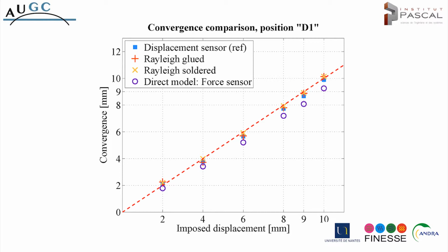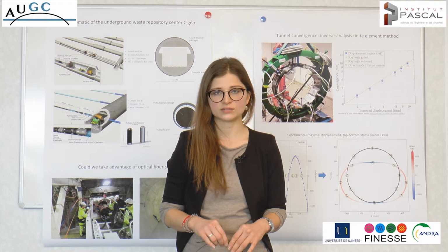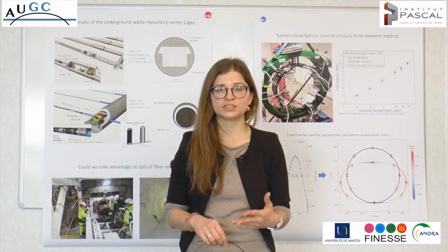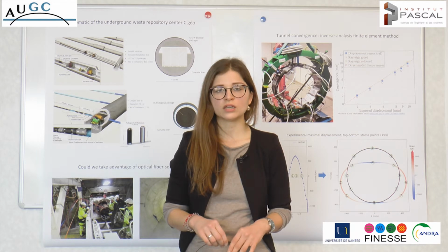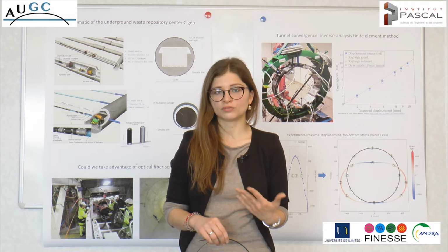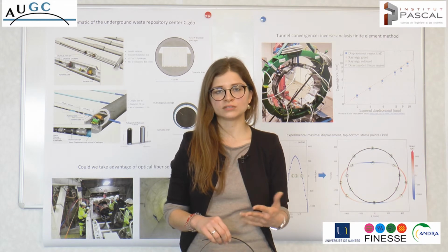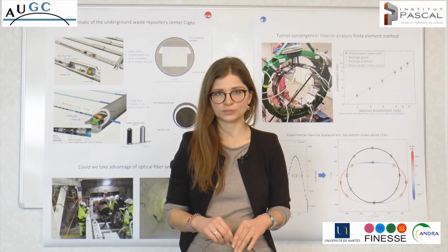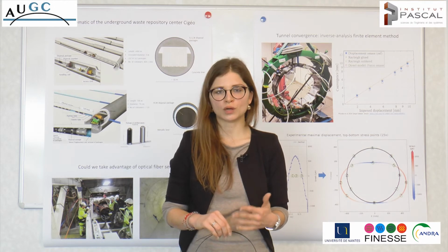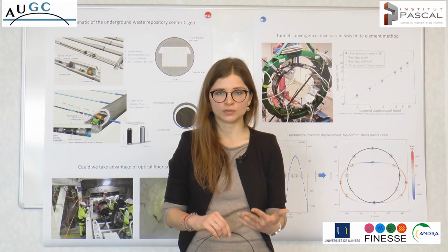And also you can see that convergence, which is obtained by optical fiber cables, is really close to the measurements taken with the displacement sensor, which in this case is the reference. In this case, we were able to prove the feasibility of using optical fiber cables to measure convergence and also to reach the representative value of convergence that is foreseen by ANDRA for the high-level waste repository cell, which is 10 millimeters of convergence. In this test, we were also able to reach the 1 millimeter resolution, which is the resolution which is expected within this kind of application.